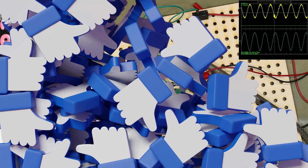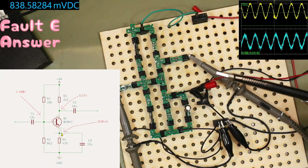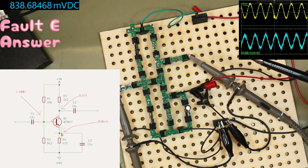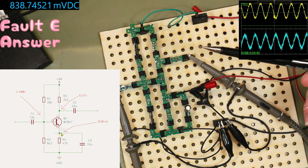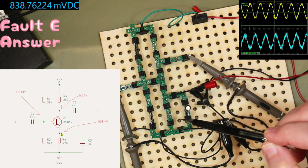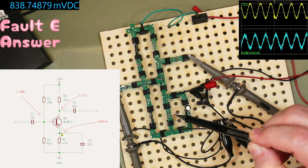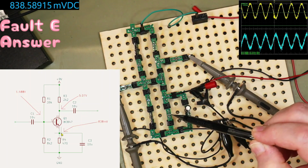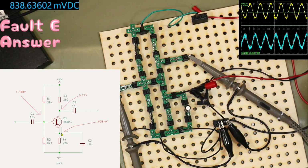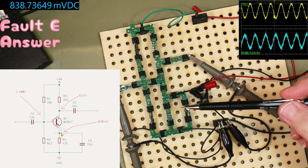So, next fault. We've got DC conditions okay, but the gain has dropped quite a bit. And that's because we've introduced a sort of negative feedback. As the current is changing in here, the voltage across the resistor is changing. That's altering the base drive, and we are getting some differences.